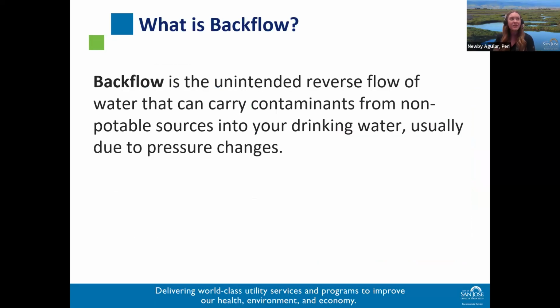What is backflow? Backflow is a general term used to describe the unintended reversal of water flow within our drinking water distribution system. There are two primary types of backflow. I'll try not to get into the nitty-gritty details, but they are back siphonage and back pressure. Both occur when there are changes in the system pressure, which cause the water to flow in the opposite direction of the norm. In the next few slides, we will review examples of what those conditions might be and events that can create pressure changes within the system that lead to a backflow situation.